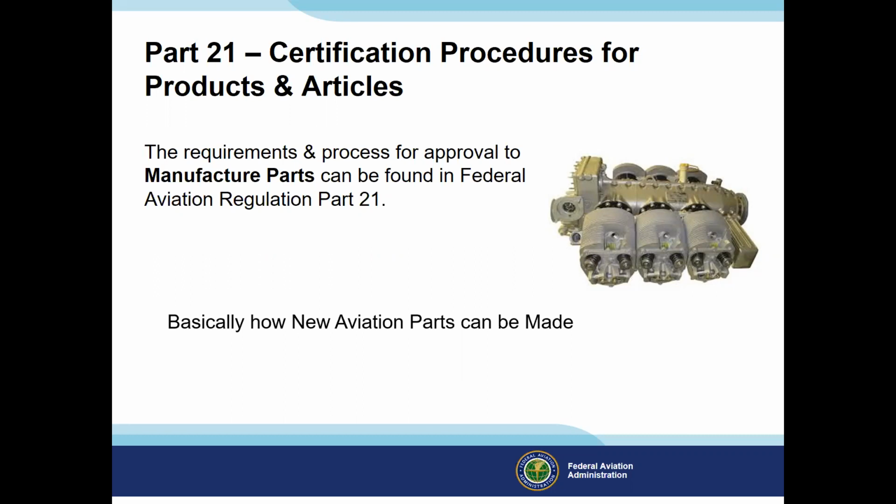That's the blanket. That's how the majority of the parts are approved: when that airplane, engine, or appliance is designed, they seek type certification for it, which includes down to the nut, bolt, and sometimes screw, what part is approved for use in that product. Next slide, Gary.